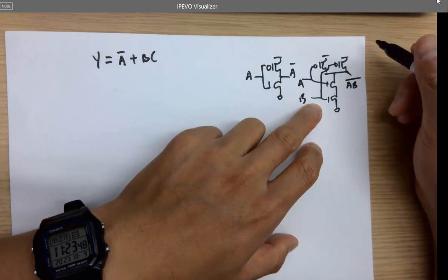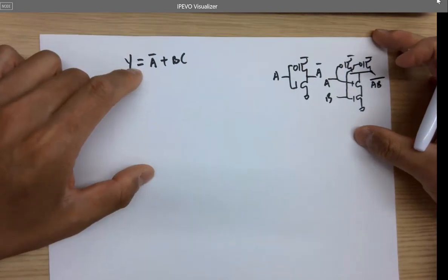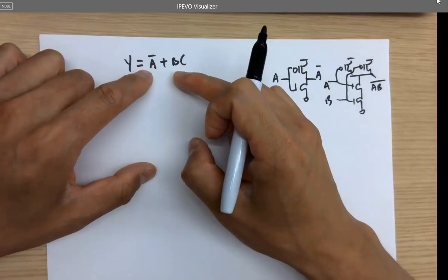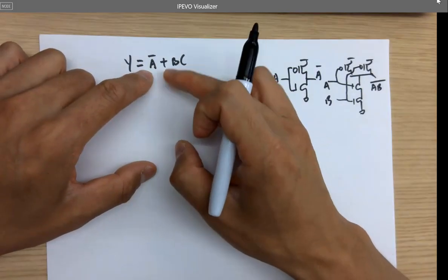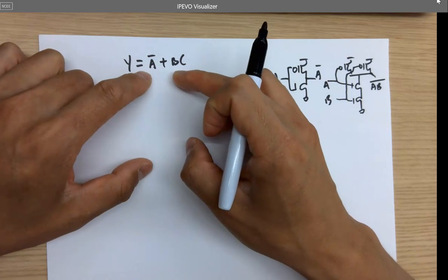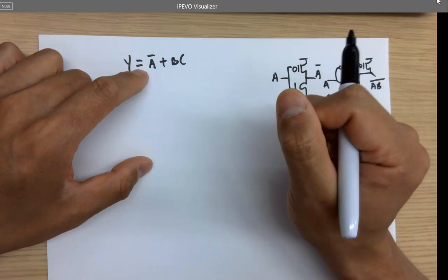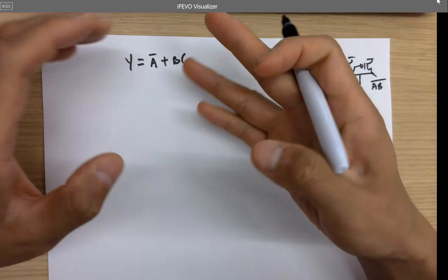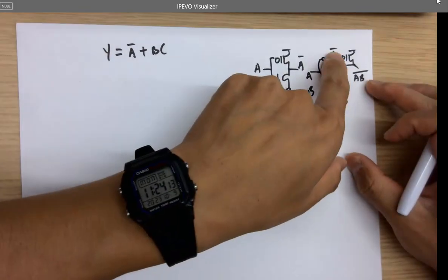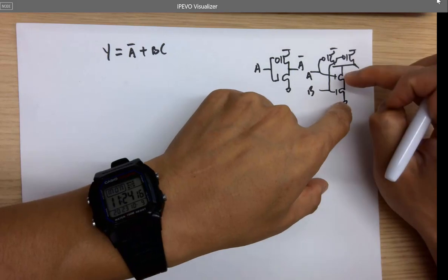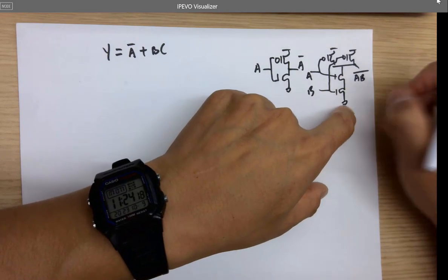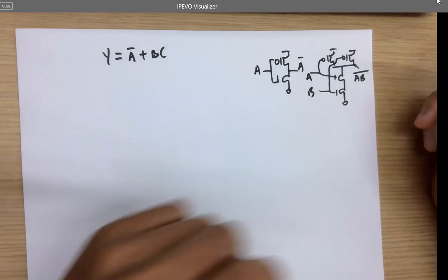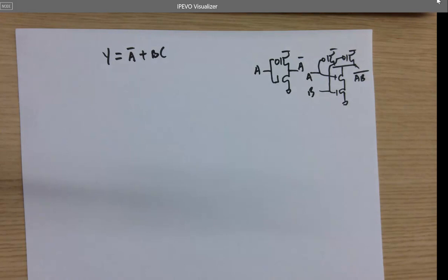Okay, so in order to design the circuit using transistors in a similar way for this logic, we probably prefer a bar on the top, but we don't have a bar on the top. Can we make it up? Now, if you don't have a bar on top, it's kind of difficult to design a circuit like this, because after you put PMOS on top and NMOS at the bottom, eventually the logic here will be inverted. It's just the nature of the circuit, and not change it.